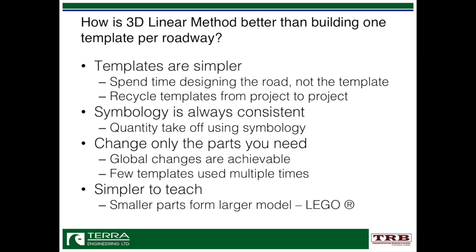The symbology. Now, for Autodesk users, the layers that will come on. Layers and symbology and levels are all interchangeable terms. Because the templates are built consistently, the way they are visualized comes out exactly the same every time you use them, which means you can do digital quantity takeoffs en masse for an entire model if you use the same templates. It's very difficult to manage that if you build a unique template per scenario. You have to ensure the symbology matches for every point on that template. But with a simplified template, you always get a clean, reliable result every single time.